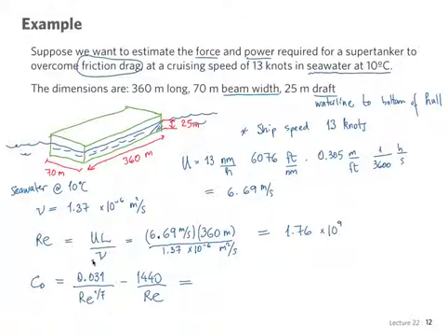Well, it's going to make very little difference, in fact, because if you see, this is 1.76 times 10 to the 9. If I put it in here, this is going to be a tiny number. But it's mostly going to be the turbulent part that contributes. There is a part of the boundary layer, because the boundary layer always starts from x equals 0, right? And we used x in our Reynolds number. It was Reynolds number with respect to x. So this beginning part there will be a small area of laminar and then turbulent, always.